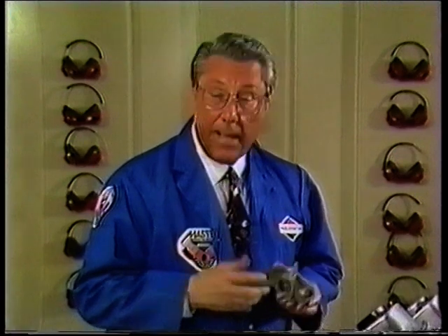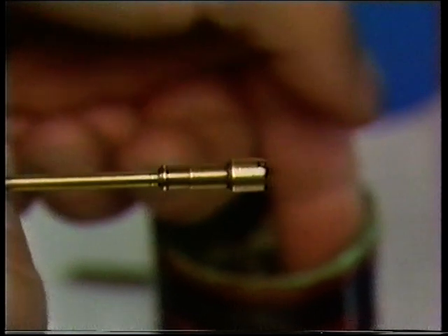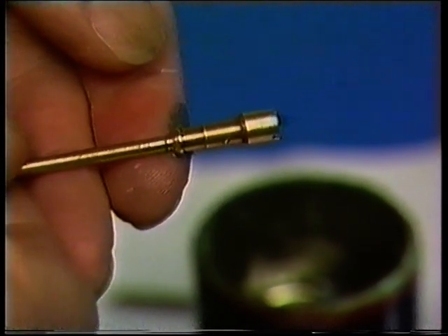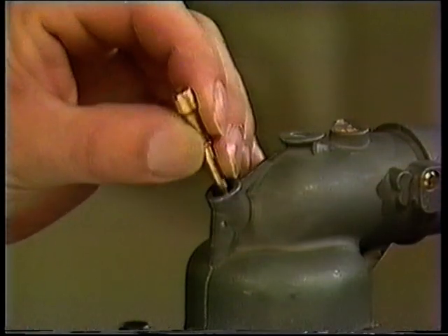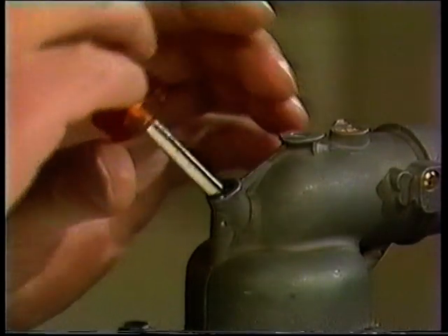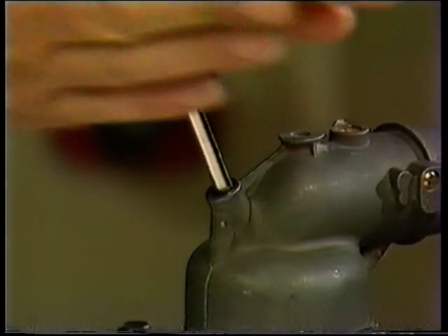If there is any defect, dirt, or corrosion on the surface of the sealing area, either the brass tube or the carburetor casting, a leakage problem could result that looks exactly like a damaged or dirty needle and seat. How can you correct this? First, take the old nozzle and remove the threads using a bench grinder. Place a small amount of lapping compound on the nozzle and insert it into the carburetor's body. Using a jet screwdriver, gently lap the nozzle, just as you would lap a valve.